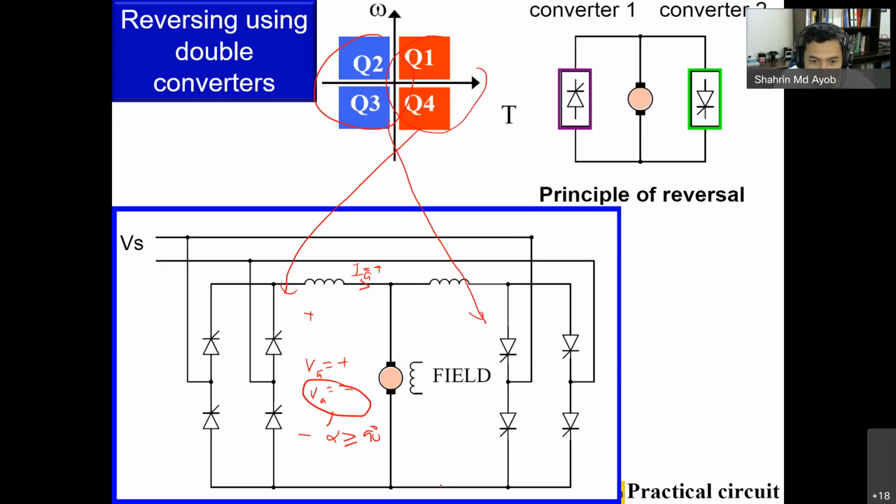And here we see that we flip the SCR circuit. So right now your current is like this. From the view of the motor, the current is going out from the motor, meaning from the motor to the supply. So your current is negative, right? Your motor sees that the current is going out from the motor through to the supply, to the rectifier circuit, so it seems like it's negative.